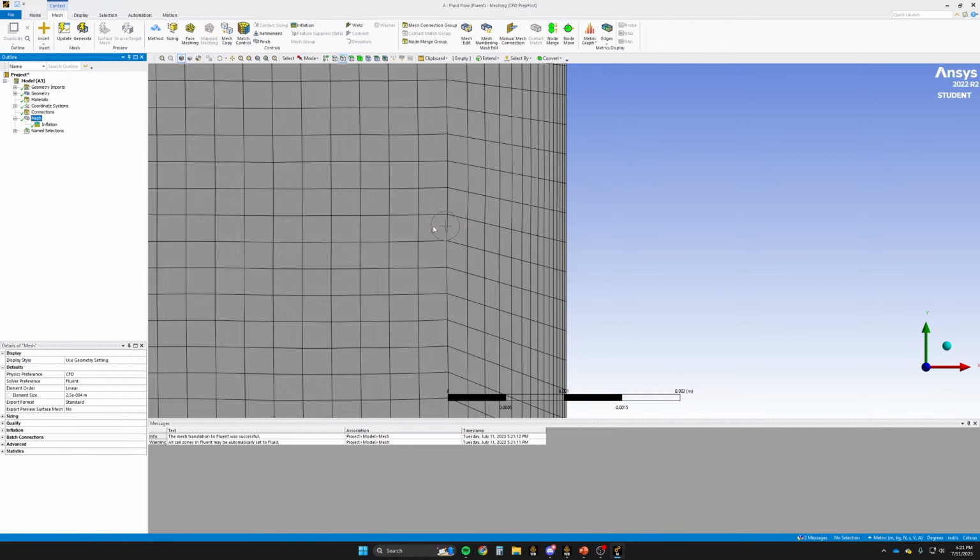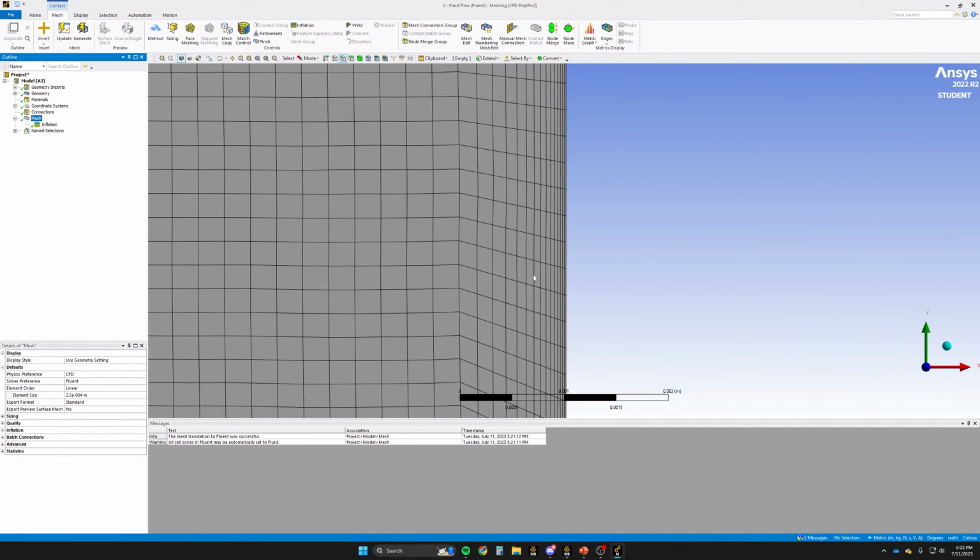We want to make sure that that transition is gradual as we move from these really small boundary layer cells into our free stream. And for fluid flow, in most cases, 0.77 or anything of a ratio of about 0.5 of cell face area between your top transition layer into your free stream is usually a good place to be. You don't want to go from these really, really fine cells directly into your bigger element size cells in your free stream. That can create problems with the simulation.